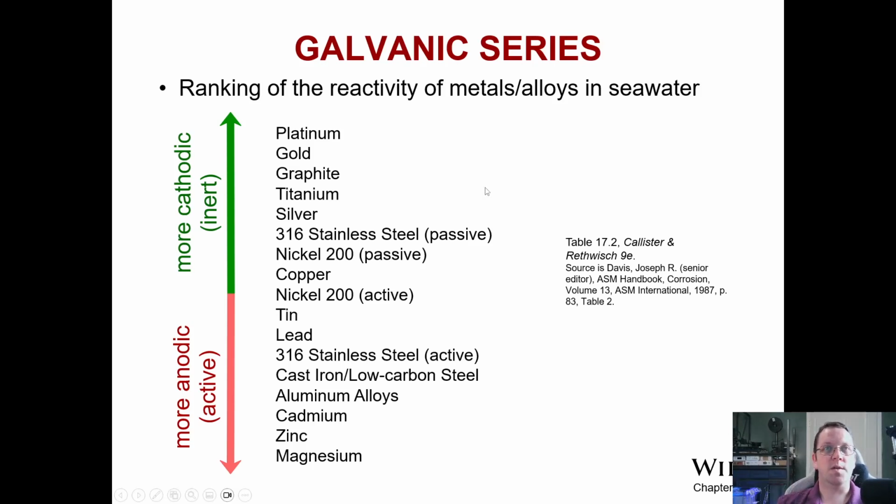So nickel, also, the reason we nickel or copper plate things before doing a chrome plating or some other material is we're trying to step it up gradually from an active material. A lot of steels and cast irons down here, we plate them with copper or nickel, sometimes back and forth, to get them up into this range, and then we do a stainless plating or some other material, titanium, some other coating, chrome, all sorts of things like that.